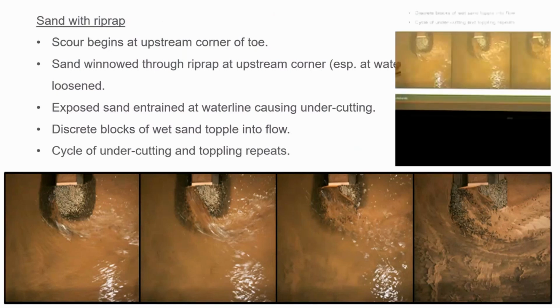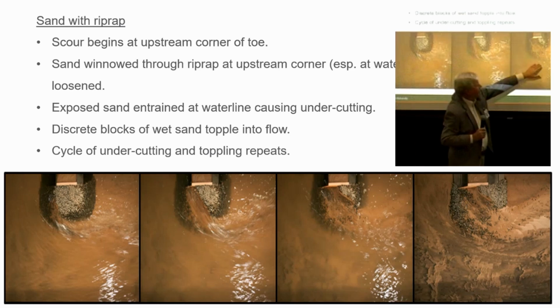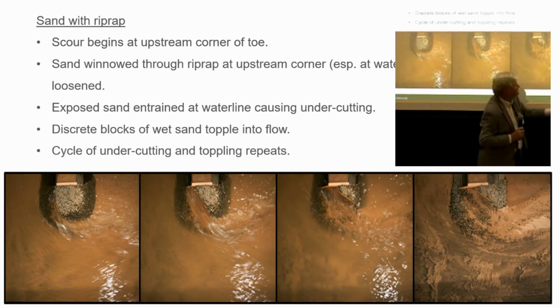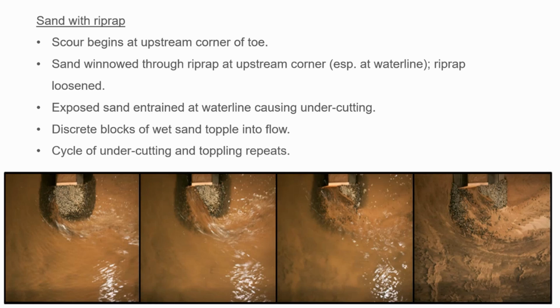So the nose, which was erodible, scour begins at the upstream where the velocity is greatest. Turbulent structures here, and very quickly you can erode through, and you end up with a failure that looks like this at the end. And what we found is the strength of the soil governs, or influences, the scour depth. And the soil didn't fail in this particular case by slope stability, which a rock pile would. You don't get undercutting of a rock pile, you get slope stability issues.